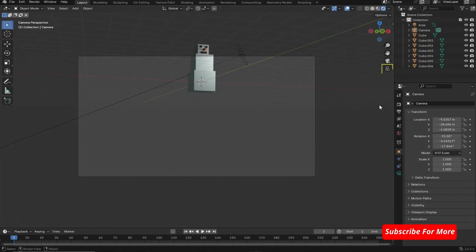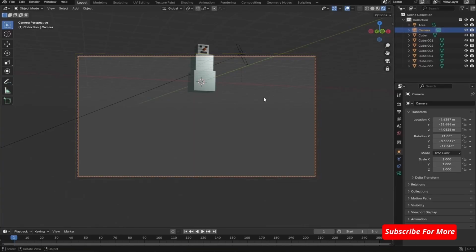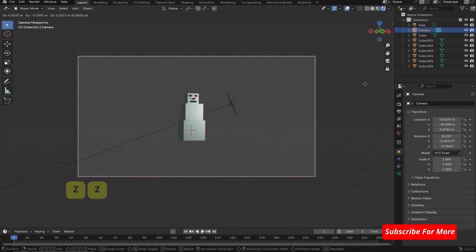So first click on this icon to lock it. And now click on this camera. So now you can see it is selected. And now press G on your keyboard for grab. Now you can see we are moving this camera anywhere we want. If you want to zoom in and zoom out, double tap Z on your keyboard.